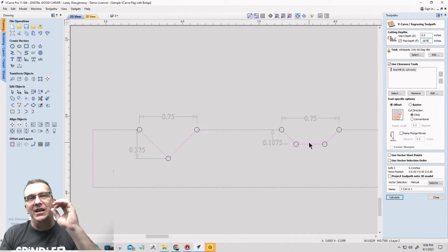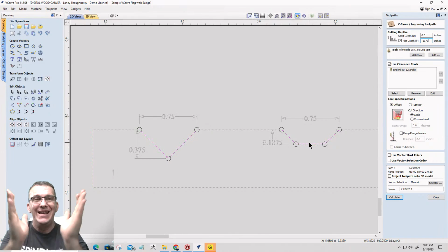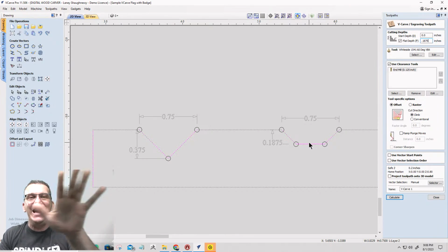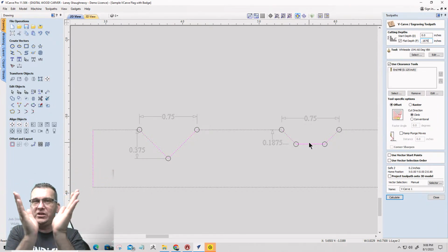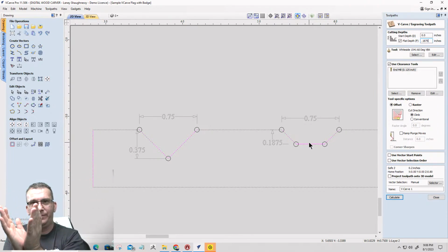If a part of the cut would have normally exceeded 3/16 of an inch, 0.1875, that part will get limited to 0.1875. Everything else in that V-carve that would not reach 0.1875 will get cut to its normal depth.